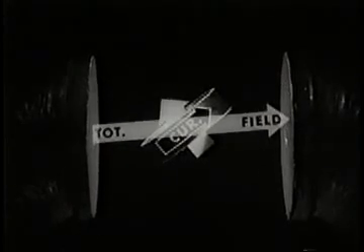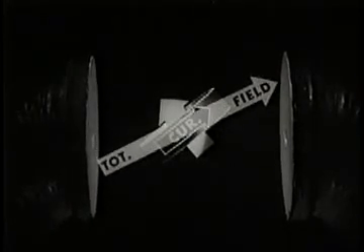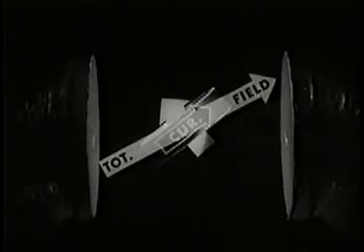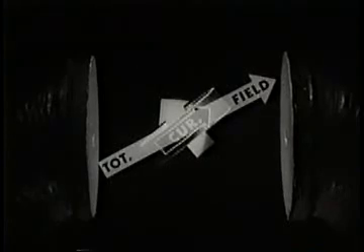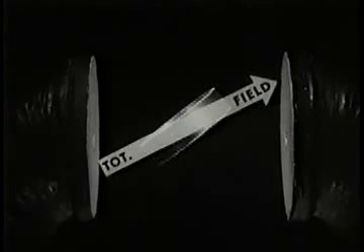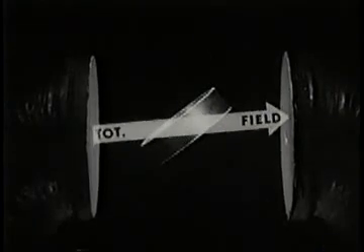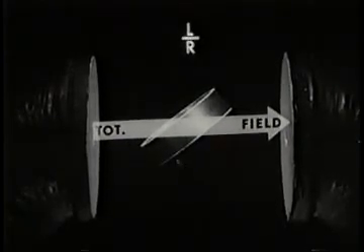The point to notice is that the field is perturbed in such a way that the rise of flux linked by the loop is reduced. If we stop the loop rotating, its resistance causes the induced current and induced field to decay, and the total field relaxes back to its original form in a time that depends on the ratio of the inductance and the resistance of the loop. This is the magnetic relaxation time, which gets longer as we make the resistance less.